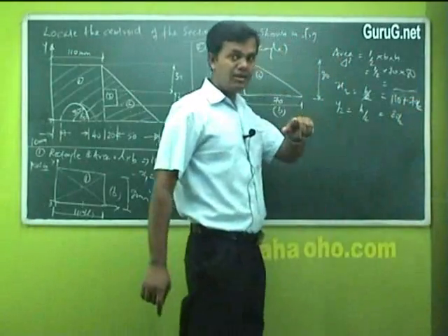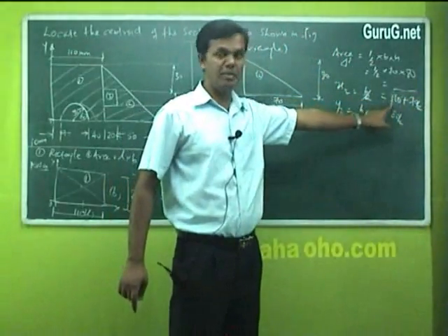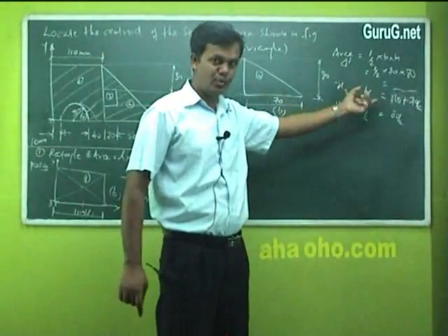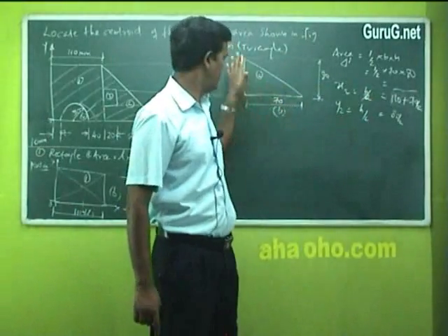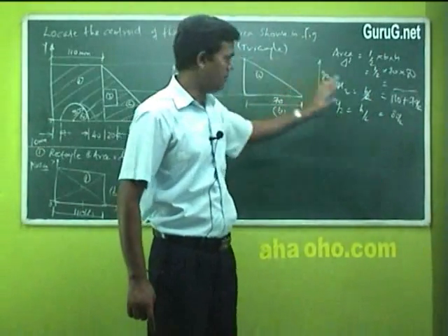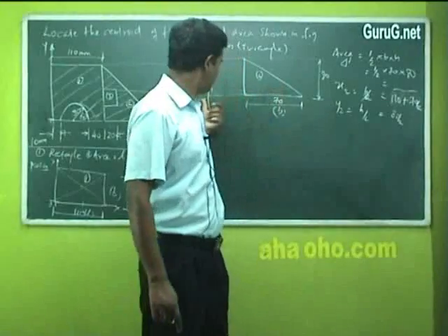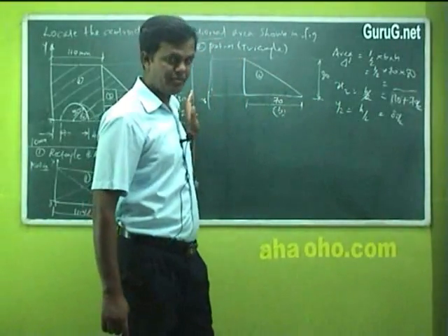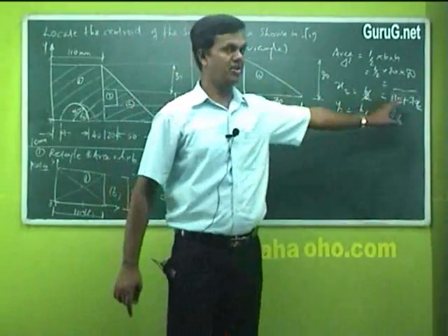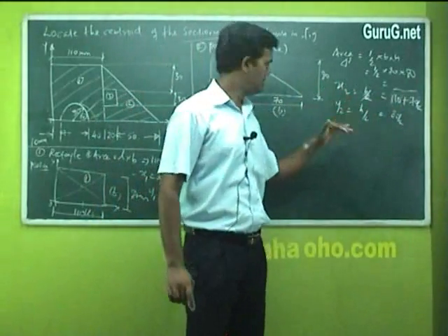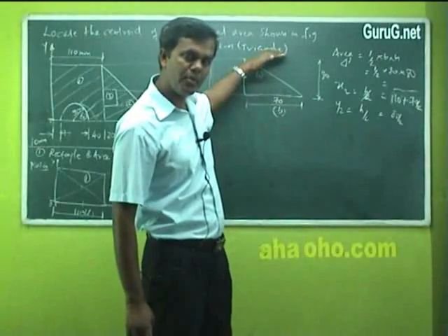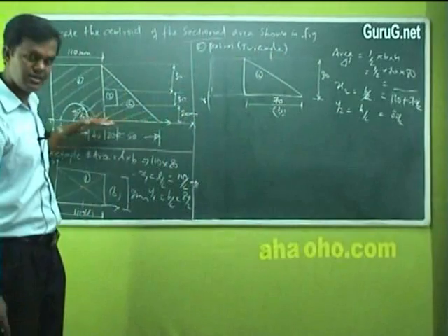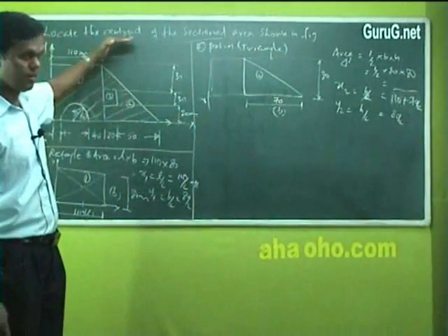You have to understand why we have written 110 millimeter here. Since the formula is only b by 2, breadth by 2, and the breadth is only 70, I am talking about the triangle. But 110 millimeter is from this base, that is the YY line, the leftmost corner line. 110 plus 70 by 2, that is the rule. Likewise, now what about Y2? Why are we starting from here? Y is taken from this base axis. From here only we are going up.